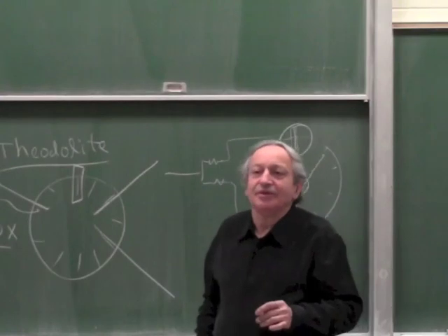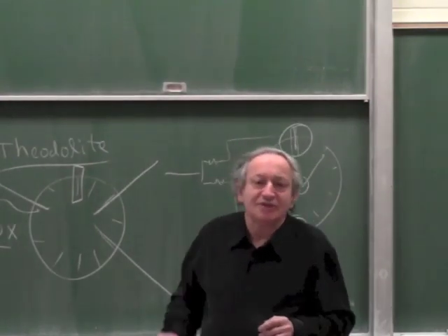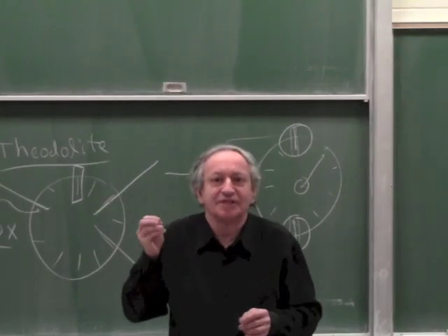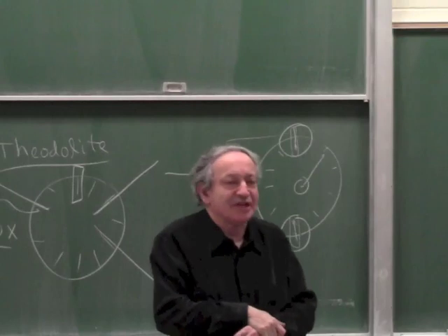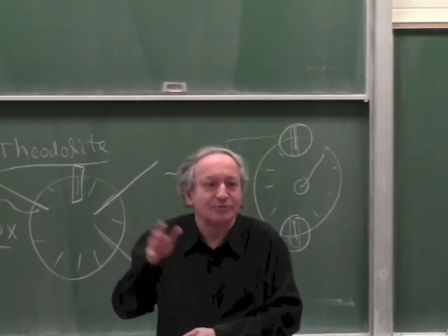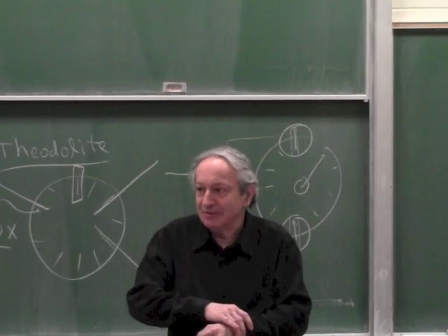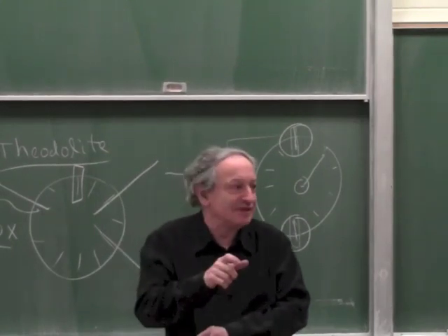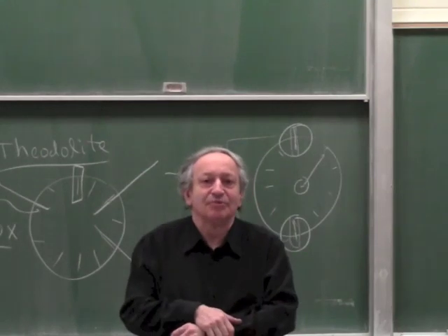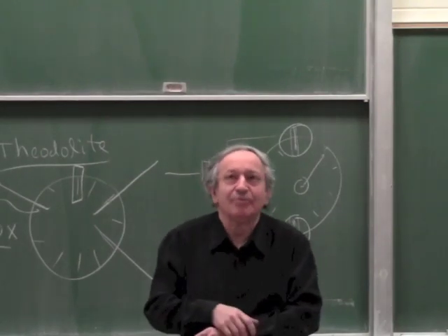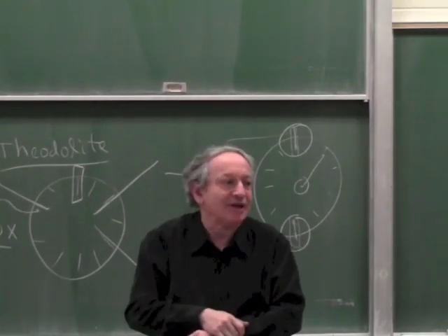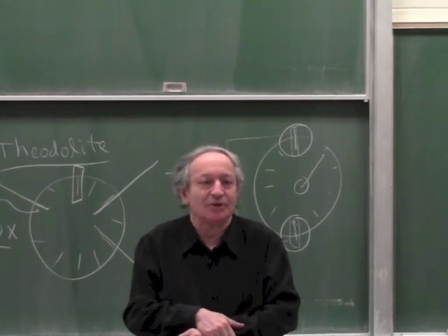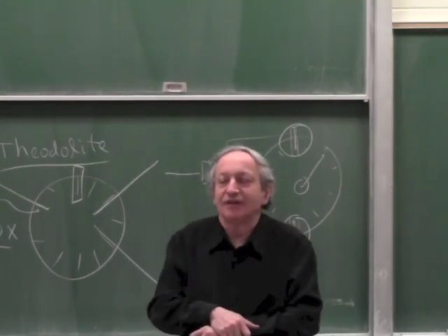We said the best way to get rid of noise is not to use a DC or what's called a CW, continuous wave light source, but modulate the light source. Because then you can pick a very high frequency which doesn't exist in the room, say 100 kilohertz. And we went through several times with this calculation that you can put a bandpass filter after the sensor, so it only sees light modulated at 100 kilohertz, way above the flicker of fluorescent, way above moving objects. And that is the most effective way to eliminate noise in optical sensors. But why is it difficult to do in a camera?